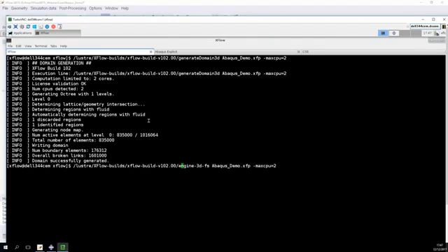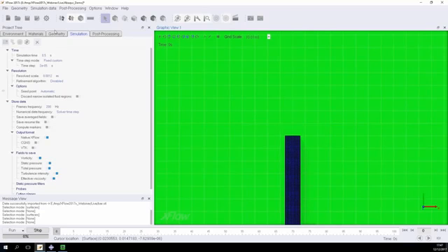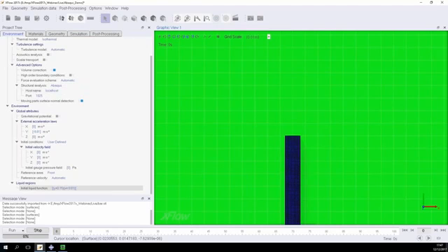And now we're going to execute the engine 3D FS, which is the free surface solver of XFlow. As you can see, once you execute the solver, it's waiting for the Cosimulation engine on a specific host name, on a specific port number, and that's what we specified in XFlow.